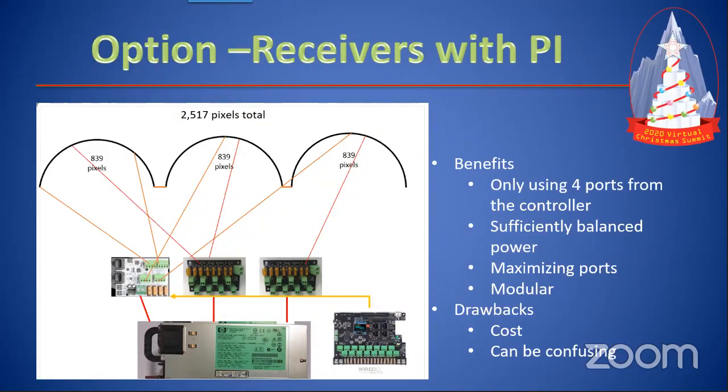All right. Then about the smart receiver: using more than one smart receiver board per port limits you to less than 40 frames per second, only if the total goes over 800 on a controller or 680 on a Falcon.